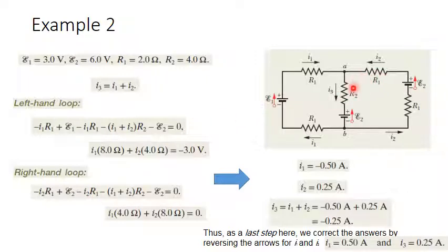Then there is a voltage drop across R2 equals I3 multiplied by R2, and I3 is I1 plus I2, so this is minus I1 plus I2 multiplied by R2. Finally, the voltage of the EMF E2, which is in opposite direction of the loop, so it is minus E2. Then we have returned back to B.